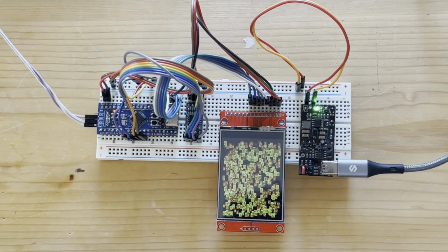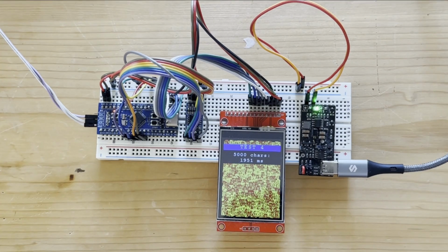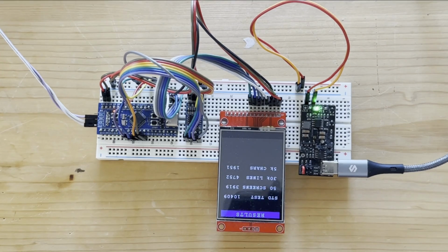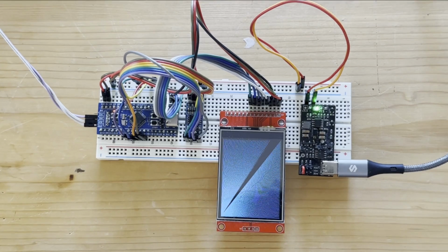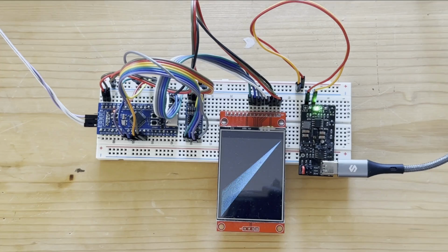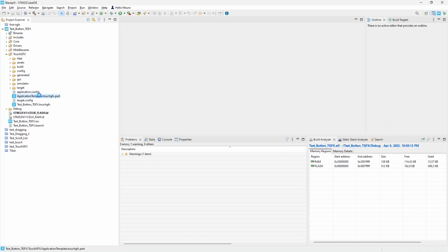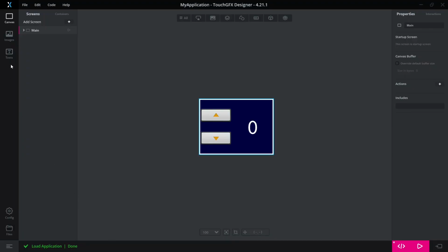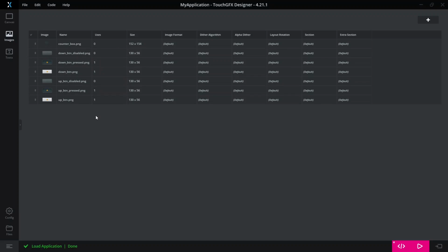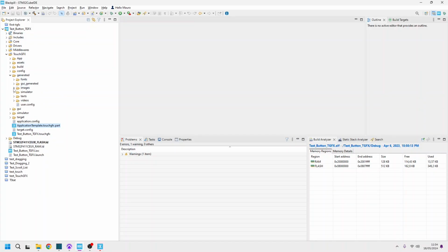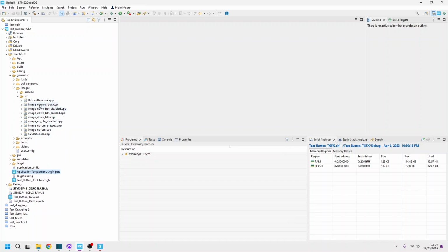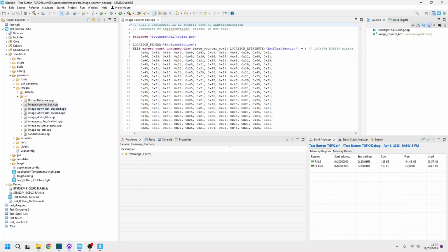SPI displays we have seen until now need pictures in RGB format, RGB 565, 666, 888, but usually we have pictures in JPEG, PNG, many other formats, but not RGB. We need to convert them. If you have seen TouchGFX, you know that TouchGFX Designer accepts usual picture formats like JPEG, and generating the CubeIDE project, it directly writes pictures in RGB 565 or the other format selected in CubeMX configuration, saving data in constant arrays to directly transfer to the display.